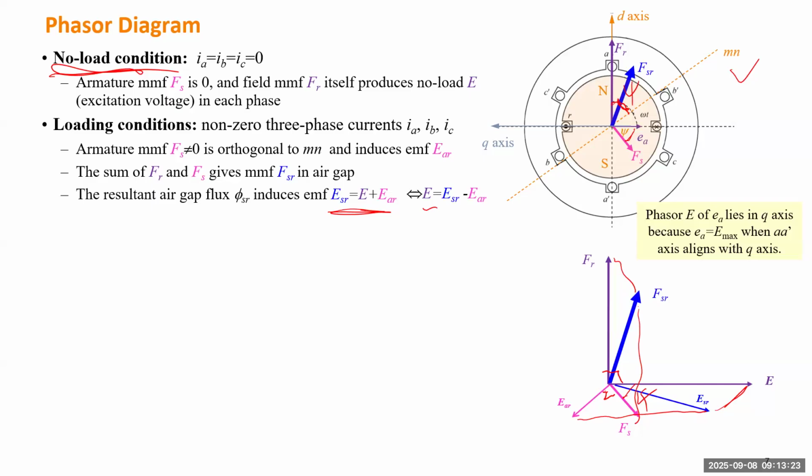So the rotor revolving will have this FR induce E. E is like an internal voltage. If you're familiar with batteries, if it's not an ideal battery, the battery will have an internal voltage, could be 1.5 volt, 2 volts, 3 volts. But when you connect the battery to an external load, depending on the resistance built up inside the battery, the voltage you can measure at the terminal in the circuit can be lower, usually slightly lower.